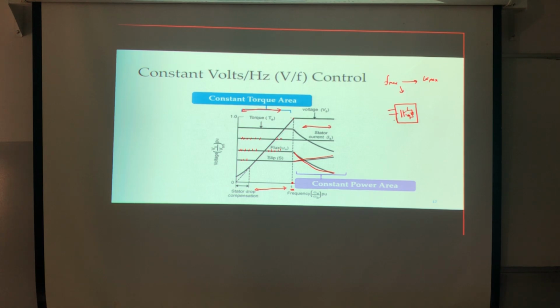Now, the input for the inverter is DC, and the output is AC, variable voltage, variable frequency. Either this inverter, for example, can adjust the frequency from F minimum to F max. So in this case, the maximum frequency is controlled by the inverter.